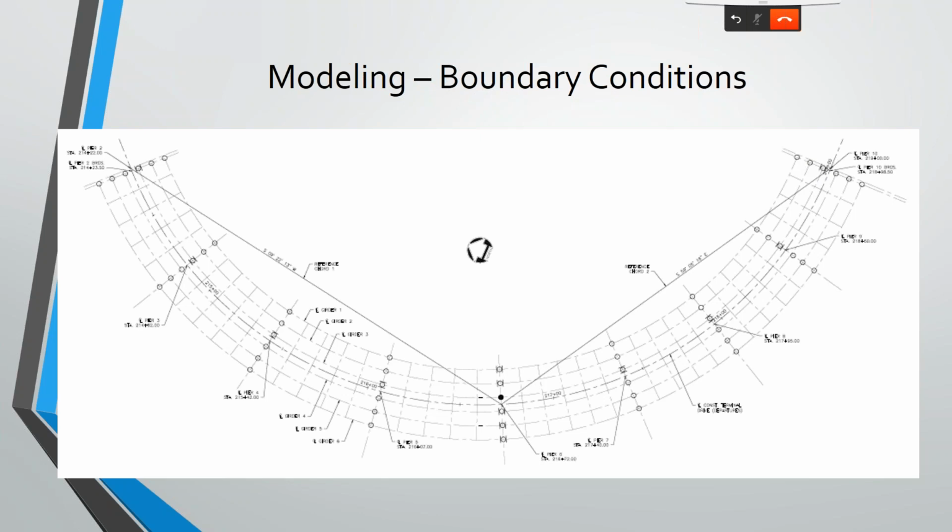In our case, we were able to get away with a strip seal joint, and those provided a lot more movement capacity in both transverse and longitudinal. But if you get to a very long structure and you need a finger joint or something modular, do watch out for that, because transverse could become a big problem there.